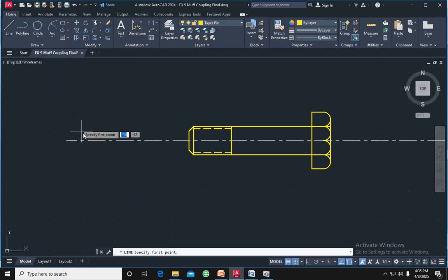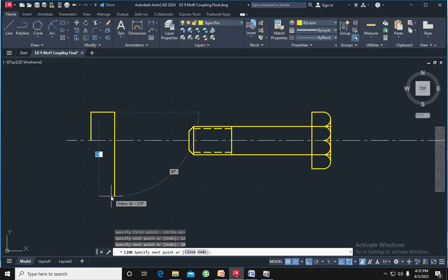Okay, we go to line and click here, go click the line and ortho command. We have to go in position. Its horizontal distance is 12, its thickness is 10. Next we have to draw the downward vertical line, which is 24, its horizontal distance 10, its upward direction 12. Okay, we completed.